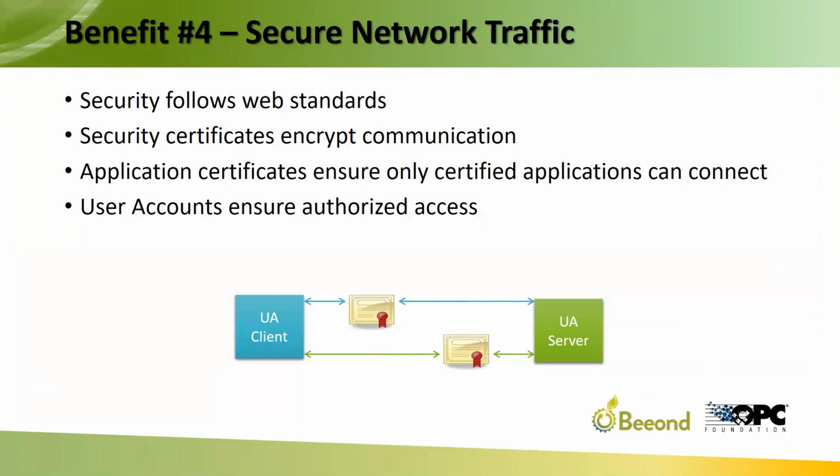The one aspect, and we go into details during our training, is that security is an often misunderstood aspect of OPC UA. OPC UA defines the specification and the implementation and the certification and the validation. It's not just a standard on paper. It's a reference implementation of how to do it. But the algorithms to use and the way you actually enforce and implement security is basically up to the user, or up to the capability of the device that the OPC UA implementation is running on. So there are different levels of security.